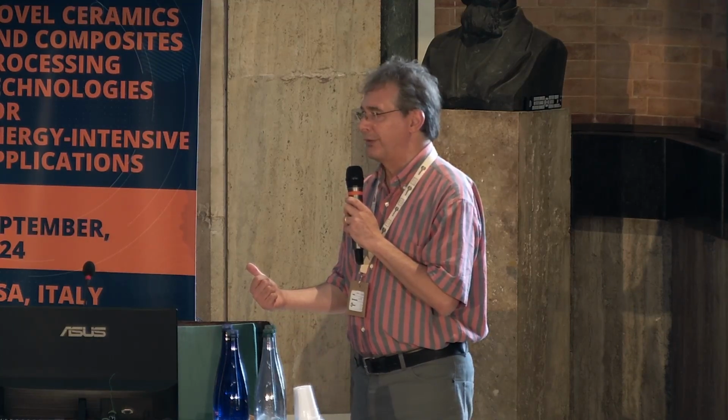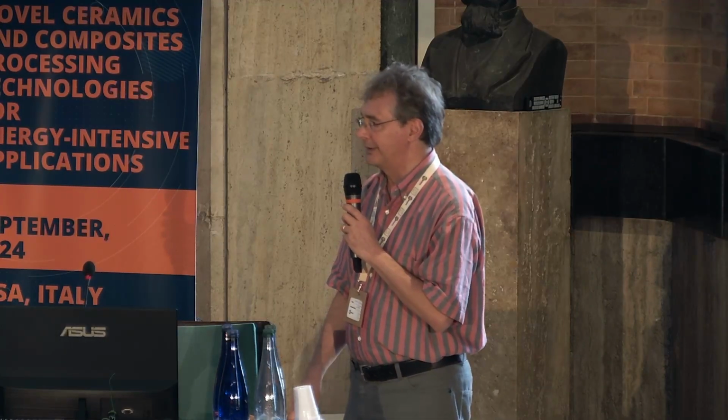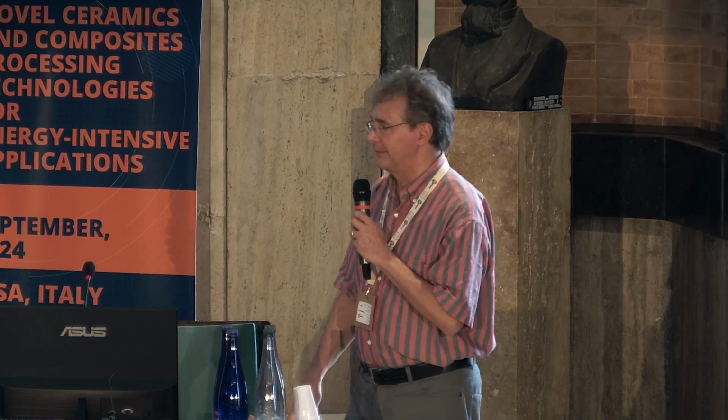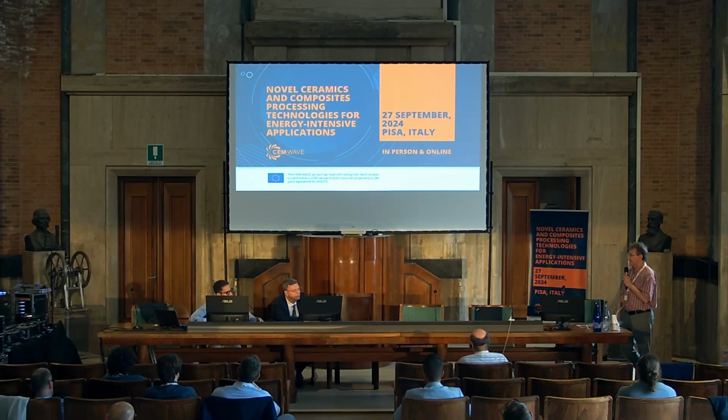No, but I mentioned fracture toughness with a chevron notch. Well, with a notch, yes, with a notch. Yes, yeah. So the filaments are 350, 400 microns. So I'm not sure chevron notch will be useful. Well, chevron notch, yes, but just a notch, because in ceramics it's difficult, in fact, to cut a notch, because they're very hard material.